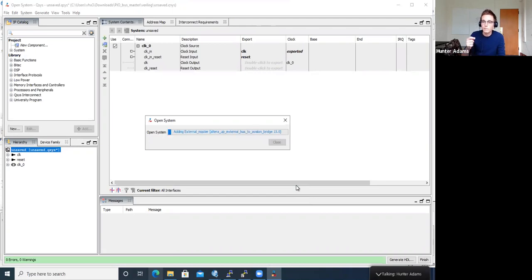That value goes into a Busmaster, which does a bus write to a PIO port that lives at the same address as the onboard LEDs. So we can send the number 10, and the binary representation of 10 will be written to the onboard LEDs so that 10 lights up in binary.